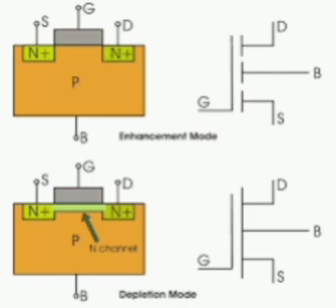Phototransistors: its principle of operation is the photoconductive effect. Coating of photoconductive materials is done at the collector base junction. It is basically a light operated switch. NPN phototransistor is faster than PNP phototransistor.